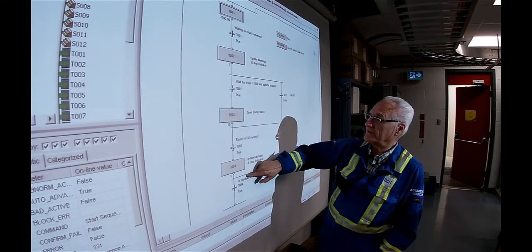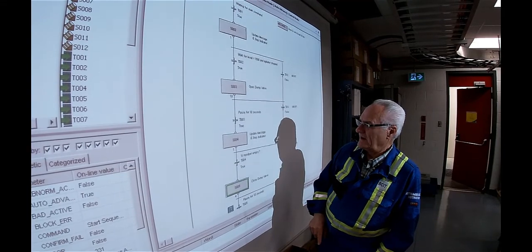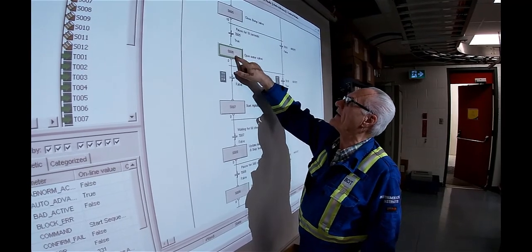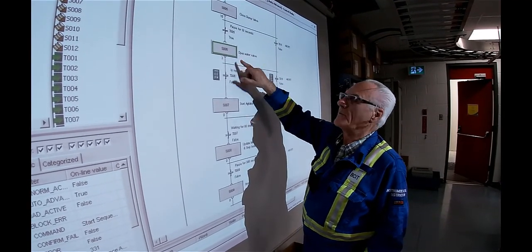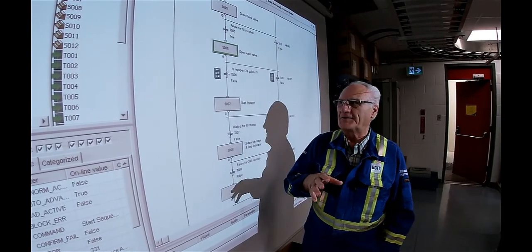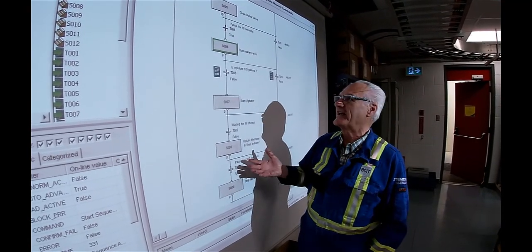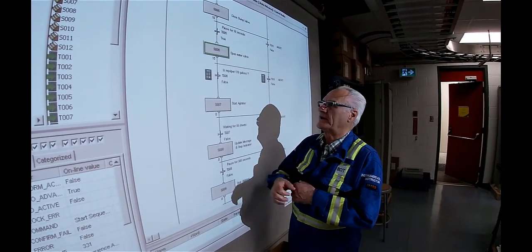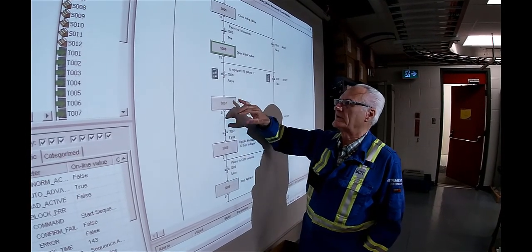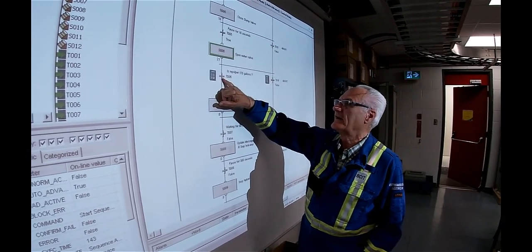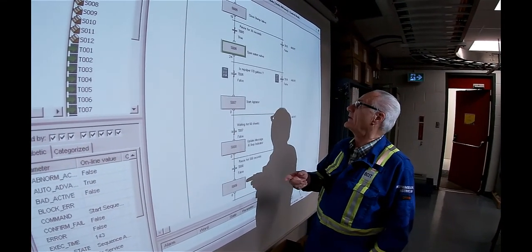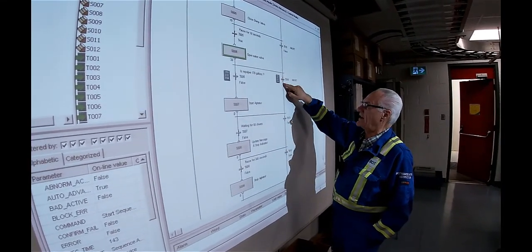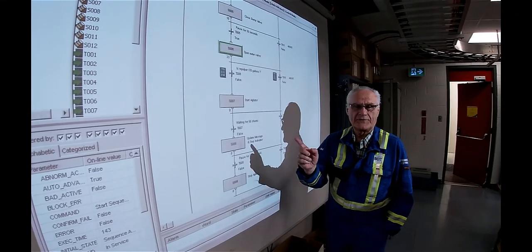So Mari, if you go back to the other screen and scroll that up. That's good. Now it's closed the dump valve, and now it's waiting to open up the water solenoid. Right now we've got the block valves closed upstairs, so it's not going to do anything. It's basically stuck here. One of the things we can do is force transitions, something we could do when we're testing. The other thing we can do is simply hit the abort button. Right now it's here, and if the abort button gets touched at any point in time, it'll go right through and back to the beginning.